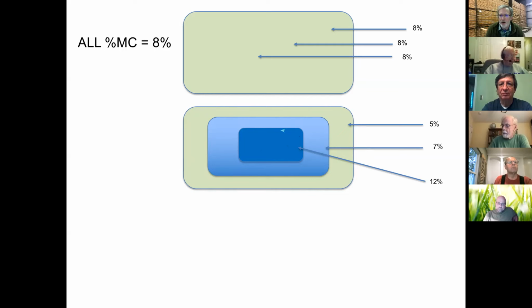to go. But be aware that sometimes it's not the average that we're interested in, it's the gradient from the outside to the inside. I don't want that piece to be more than 1% or 2% different from the outside to the inside, or that wood is going to warp on me while it's in my shop and once I've started cutting it into pieces. And this is a very common problem with dried wood.